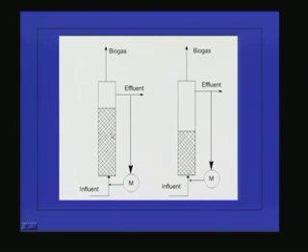So this is the example of a fluidized bed reactor. Here we use sand, coal or any plastic media as the supporting material on which the microorganisms can grow. In the reactor we put the supporting material, and with respect to time the microorganisms present in the system will get attached to the inert support material we have provided here.